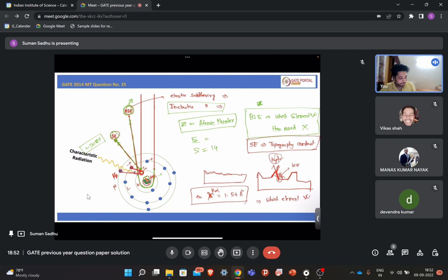So this you also know. Now we need to know how much of the element is present. For that we use the X-ray, which has a certain intensity. Let's say in your sample, one sample is pure, and one sample is an alloy. You take the intensity from the pure sample, let's say I naught or IP, and the intensity from the alloy, IA.